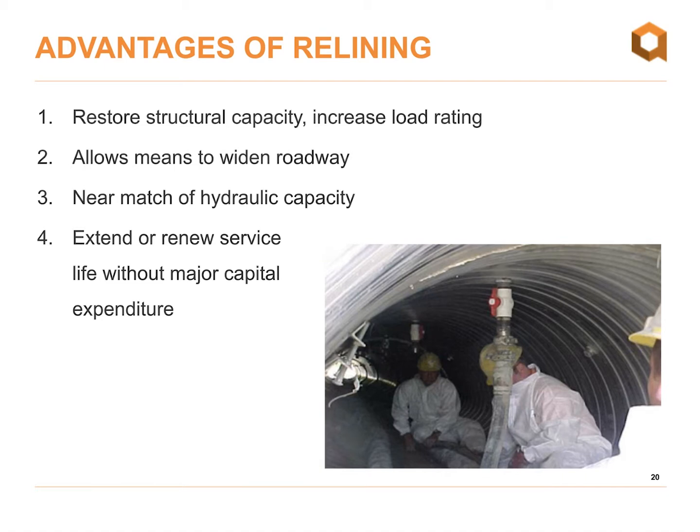So just a few key advantages of relining, primarily in comparison to those other rehabilitation measures that we've spoken about. First and foremost, of course, we can restore the structural capacity of the culvert. So we can design for whatever the live loads are, dead loads as well. We can actually increase the load rating of the culvert as well. So if we're upgrading from a service road to a municipal or a highway, or potentially if we're increasing the dead load or the extent of fill over the structure, we can accommodate that as well with a reline situation.